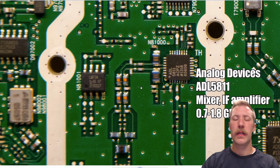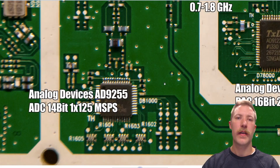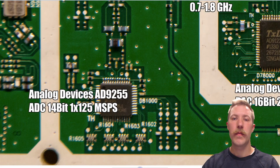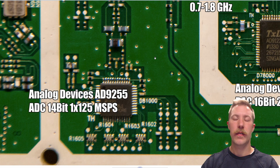I also did a detailed view on that in another video, so check out the description for that topic. Here we can see the dual lines exiting out of this before entering into the Analog Devices AD9255, which is a 14-bit ADC, which has a single line out for 125 megasamples per second.